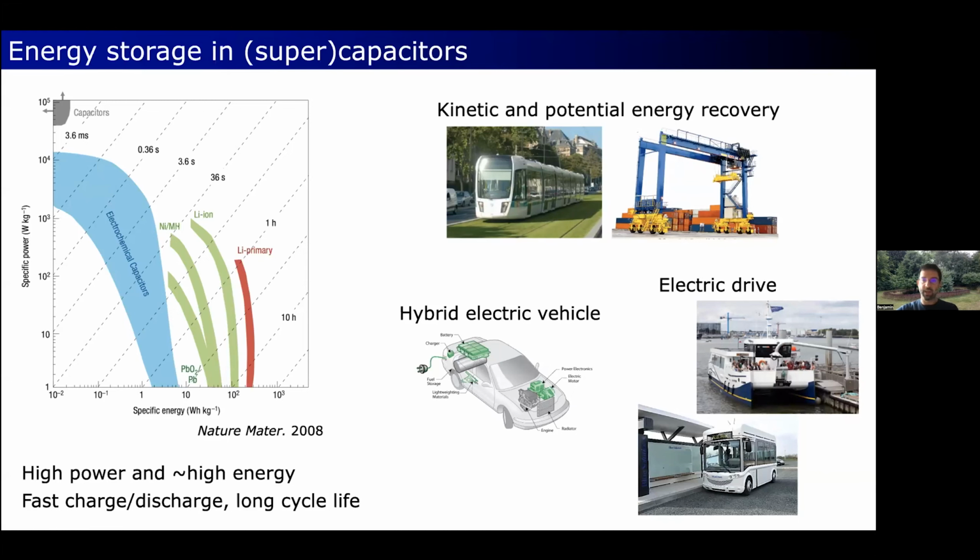when you start moving again. And here is the same idea with a harbor crane. You recover potential energy when the crane goes down. You can use that to charge supercapacitors and then use that stored energy when you lift the crane again. It's also used in hybrid electric vehicles, for example for the start-stop system or as a booster, and also for electric drive. So instead of using batteries, you can use supercapacitors, but because you cannot store a lot of energy, it's limited to specific applications where you have frequent stops and you can charge again during the stop.